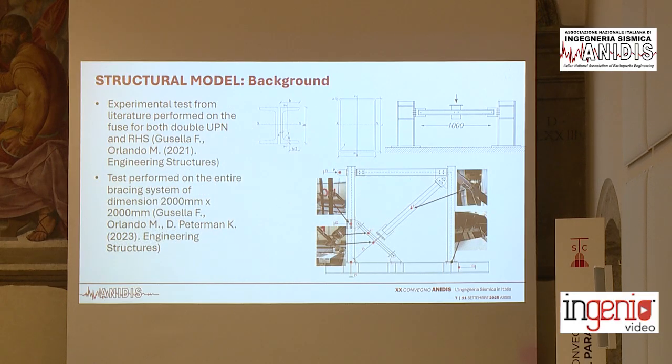Our numerical model is made based on the experimentally calibrated knee brace frames, which follows 2 experiments. The first experiment examines the structural behavior of the fuse under a 3-point bending test, while the second investigates the structural behavior of a knee brace frame subjected to monotonic and cyclic loads.